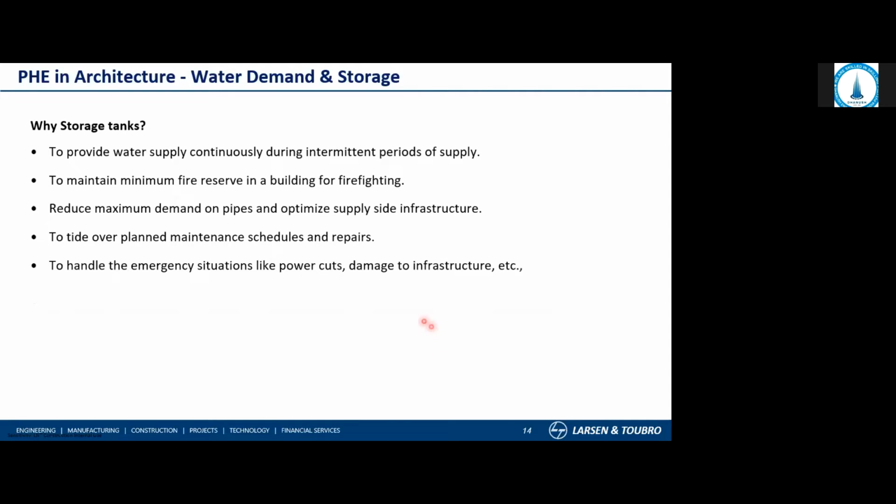Now we'll see why the storage tanks are mandatorily required for each project or each development. See, it will make the water supply continuous. It will avoid the intermittent supply. So if you have that storage, you will get a regular supply, and it will have a minimum fire reserve also you have to maintain in the building. For that also it is required, and it reduces some amount of